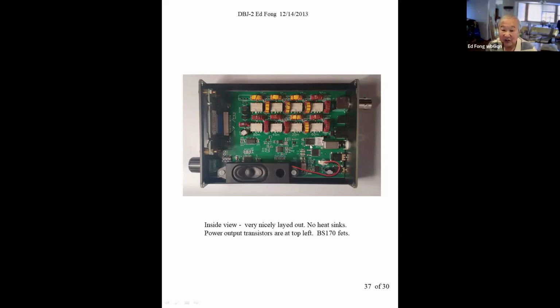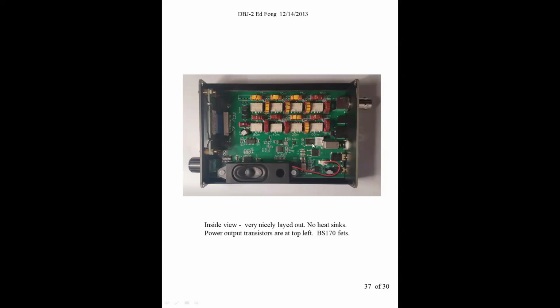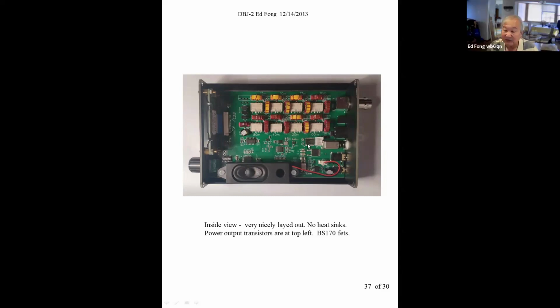Did you know there's not even an audio amplifier here? You know how they do the audio to the speaker? That's a digital chip. How do you get audio? They sigma delta modulate it. They pulse width modulate the audio, and then you filter it to get audio. That's how clever it is, because that's not an analog chip. That's strictly a digital chip.